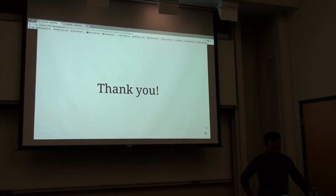Yeah, so one way to think about this is, actually, this brings us to the inspiration for the distance transform function. It's an edge-based visual odometry paper by Xiaoji Shen in ICRA 2016, in which they get edge maps of consecutive keyframes, and then they're optimizing, instead of catenary curves, 6 parameters like an SE3 transform. And the whole problem they're trying to solve is the same: get a higher recall edge detector, and use their distance transform to avoid the problem of correspondences.